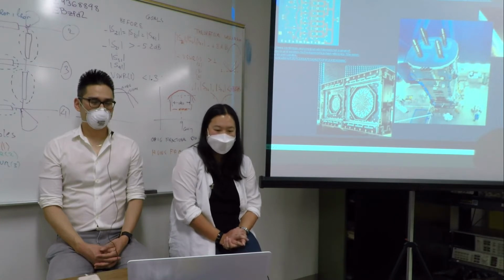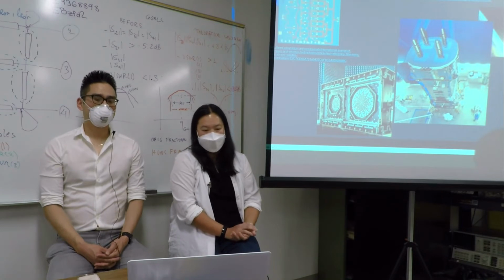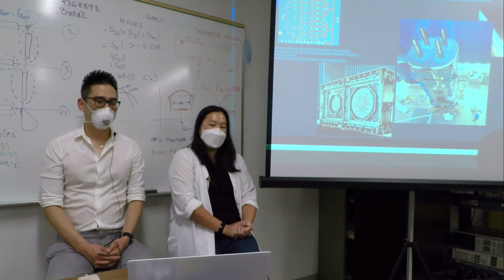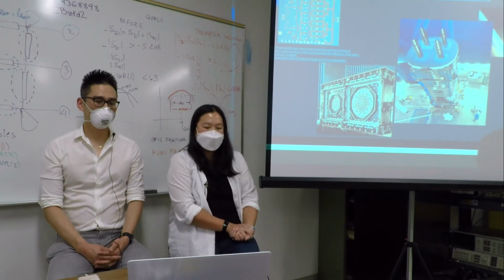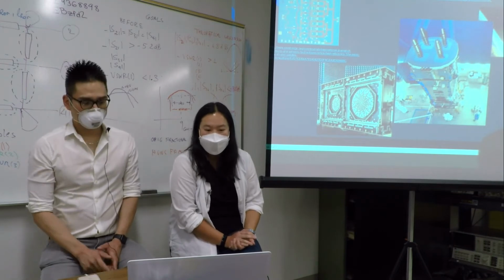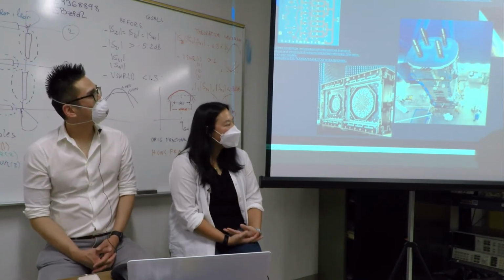So on the left, I have an example of a MMIC. We've been talking about that. This is not one of our MMICs. This is from a paper from Cambridge, but the principles are basically the same. You have a die. I don't remember exactly what the size was, but typically the die that I've designed have been like 2 by 4 millimeters. This one looks pretty big, so it could be more square, maybe 4 by 4 millimeters. This looks like a PA.